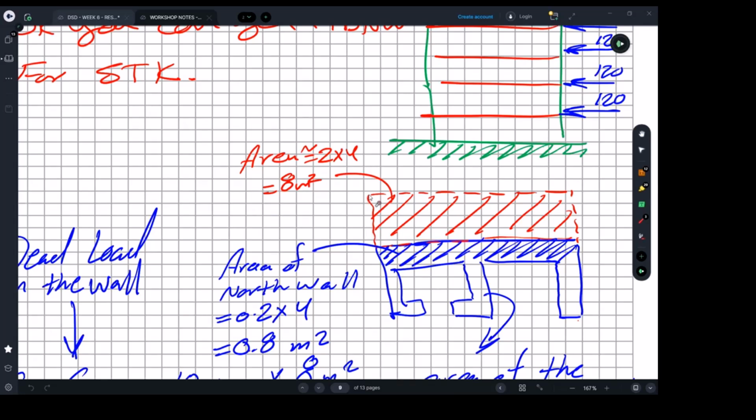The pressure is the thickness of the slab by the density of the concrete, which is 25 by 0.2. That will give me kPa. kPa by the area will give me the force that will come from this piece of concrete for one single level. I will multiply this by 10. That will give me the full load for 10 stories.